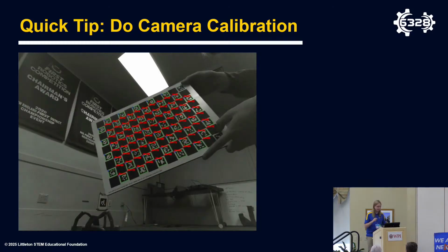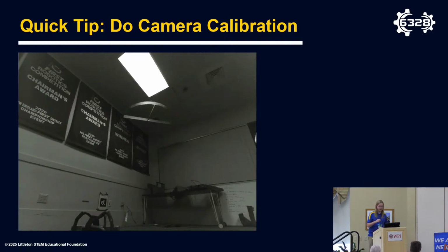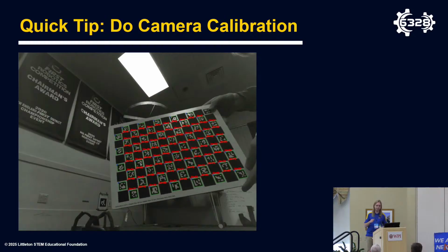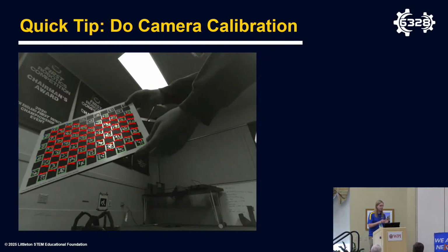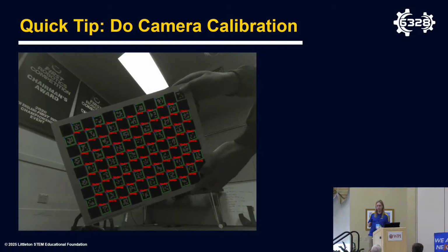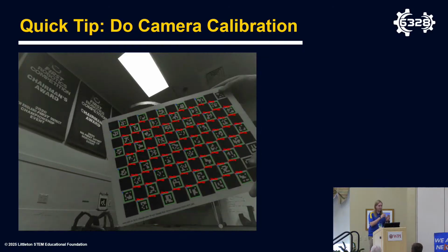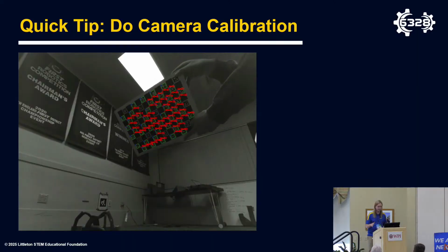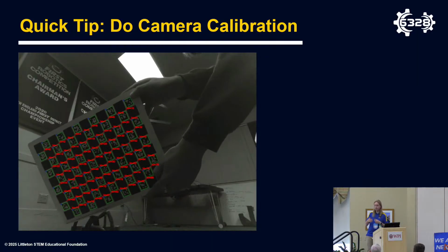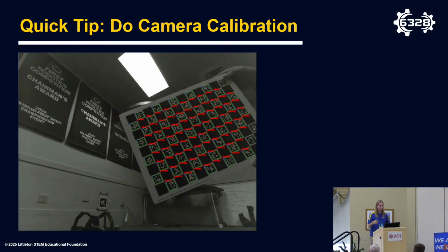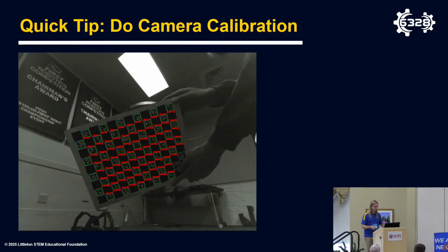Also important to keep in mind, most cameras are built to relatively poor tolerances. They are very much consumer grade. So expect that you will need to individually calibrate every camera on your robot, even if they are nominally the same model and lens. They are all going to be slightly different. The reason for that is that most cameras are really just not built for machine vision, so most of them don't support that.